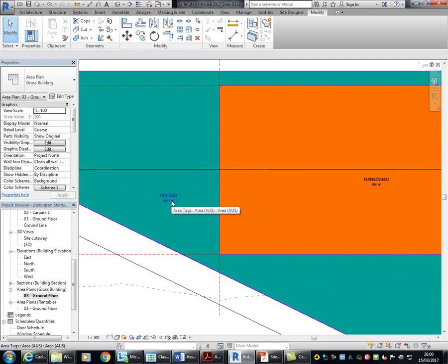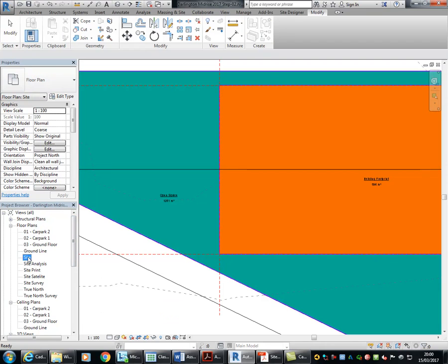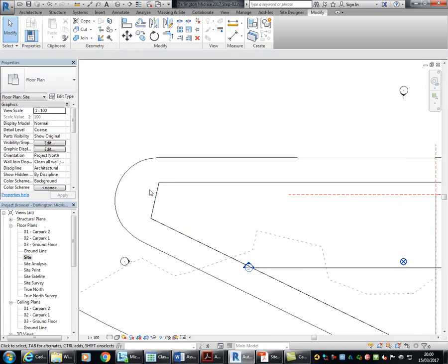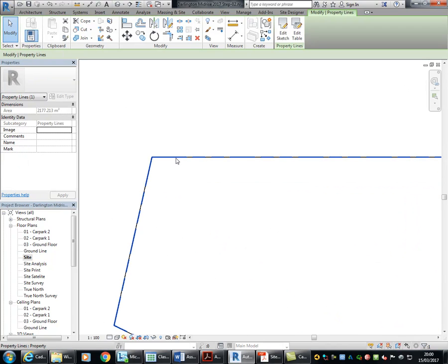schedules. So do you know that you can get the boundary? If we look at another drawing where it's not going to show those areas, I can there select the boundary object. So boundaries, site boundaries, should give you an area readout, and that's more reliable than adding together those figures that you have in an area plan, because they're rounded off. So make sure you know your site area as an accurate measurement taken from your boundary dimensions.